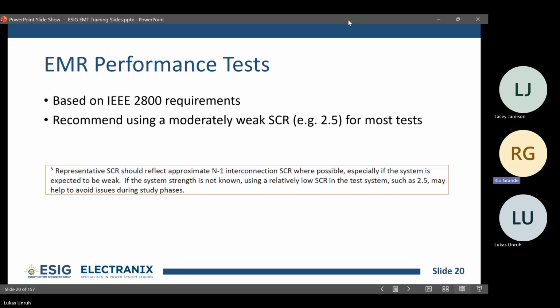Isn't it that if the X/R ratio is smaller, that means P and Q are coupled more and it makes the system weaker? Just having more coupling doesn't really say anything about the strength of the system. It can definitely pose a challenge to the inverter controls if the X/R ratio is really low. Perhaps there'll be some special tuning needed for that plant.